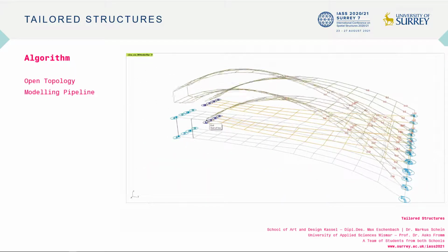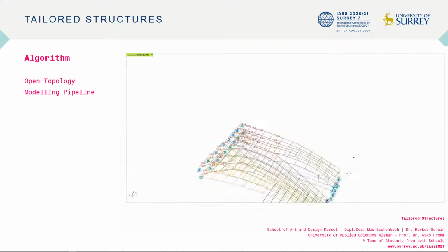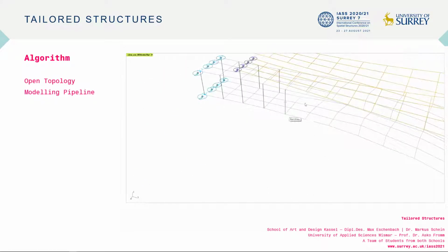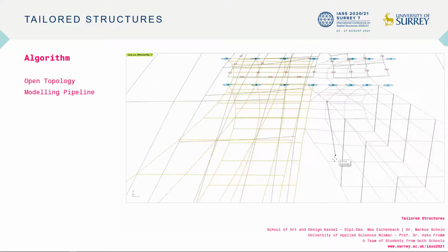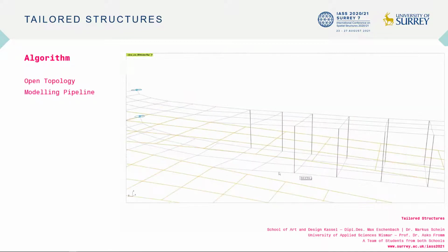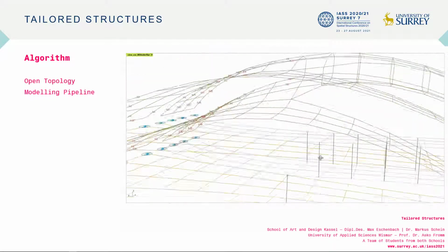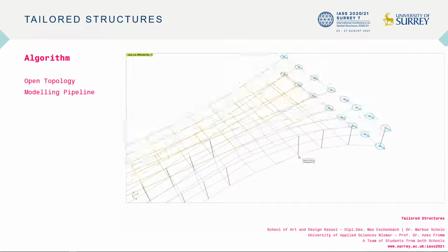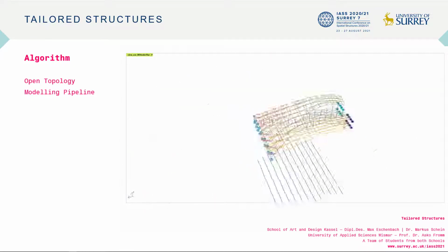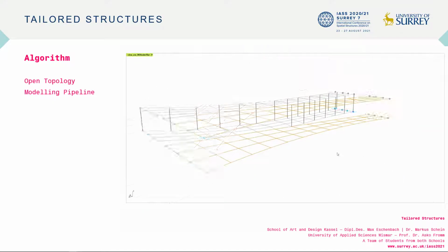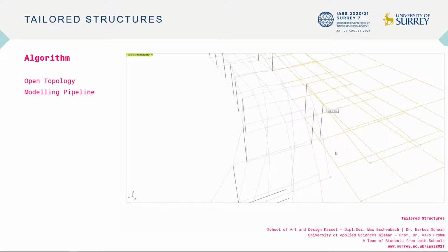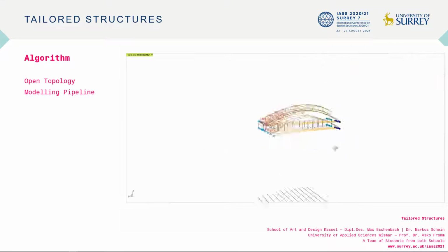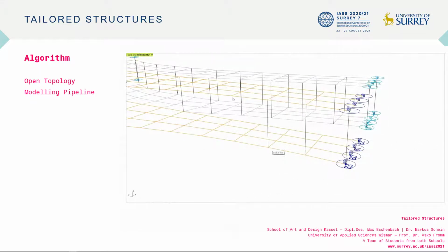The open topology modeling is based on geometrical primitives through which on one hand we can define the structural elements and nodes of our design, and on the other hand we can use such primitives to assign further properties to the structural members. For instance, selections for geometrical constraining, length is of course crucial in our context, specific support conditions and so on. And we can do this interactively while the structure is dynamically relaxed by the Kangaroo engine.